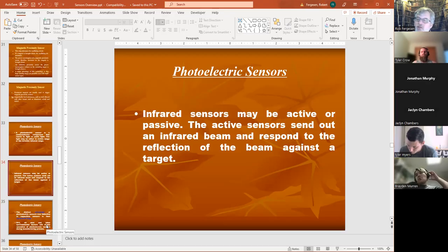In general, a lot of them are infrared. They're using the infrared range of the electromagnetic spectrum, and we're going to get into that in the chapter here, to send out the energy and receive the energy. Why are we using infrared? Well, the same reason why you would use it on your TV remote. That way you don't have an accidental trigger from a spectrum of light which is more common.